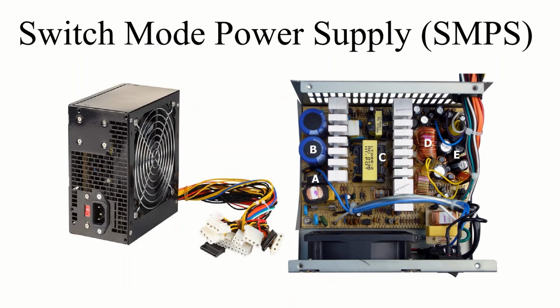We need to choose the best quality of SMPS before buying any computer. Why am I saying that? Because SMPS is also a main cause of hanging of the system while working. Actually, sometimes the DC power supply could drop for a few milliseconds, not able to provide power to the motherboard or hard disk, and the computer gets stuck and goes into hang mode. It only happens because some cheaper SMPS companies have used low quality capacitors, ICs, resistors, etc.